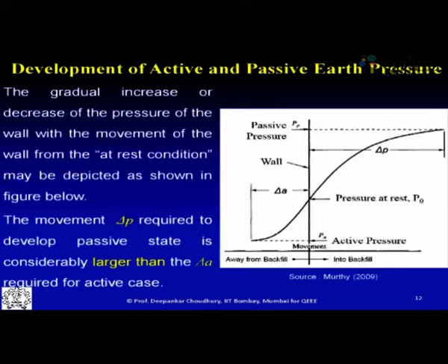So it is very important to understand whether that fully active condition has been achieved or not. If it is partial, based on the displacement of the wall because of some restriction, then one can always ask, what is the need for studying the other states of earth pressure? We can only study active earth pressure because, as I am telling, it is the most common, and we want to design for active state of earth pressure at site. But there are certain types of construction or level difference where you want to maintain, as I was showing earlier, the position of some of your important structure, where the amount of displacement or movement allowed is very, very negligible, close to zero.